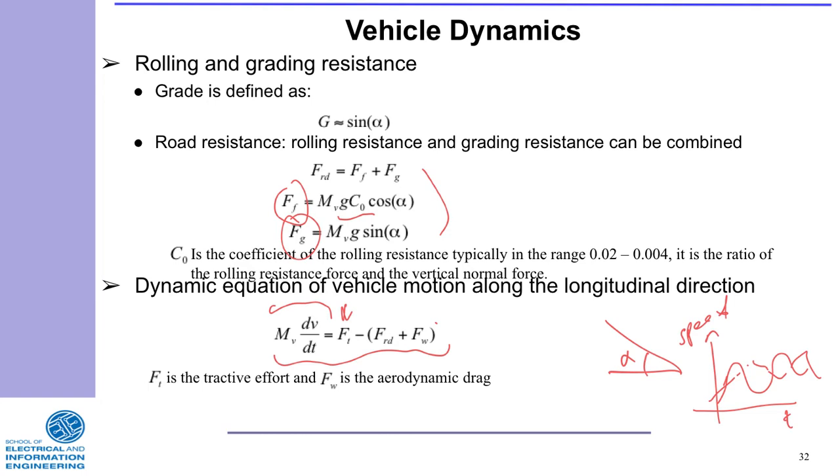One would know these forces. And let's say what's the maximum speed. Maybe the maximum speed a person could drive is 140 kilometers per hour, and based on that speed you will also have the maximum force due to the wind and so on, and maybe you get the typical wind speeds of the area, and that will give you more or less what one should anticipate to be the maximum forces. So which means you now need a combustion engine that can actually produce that force. All right, but that will just be to equalize the forces.